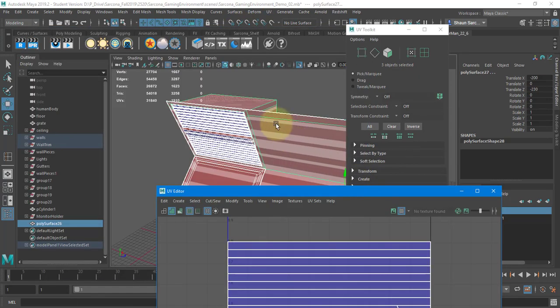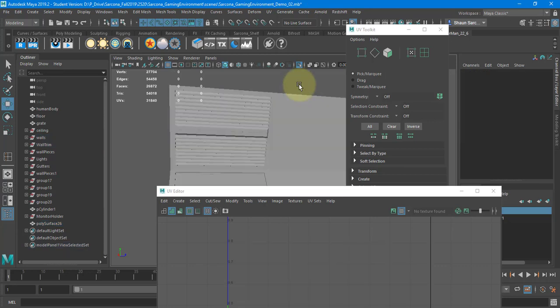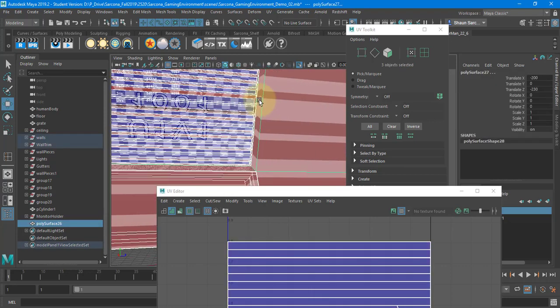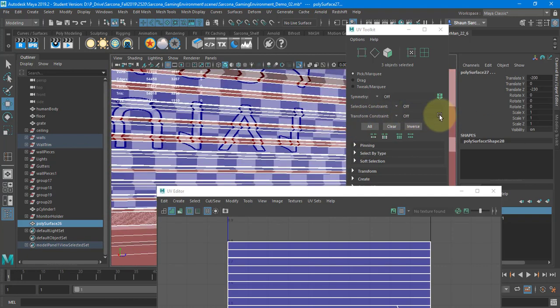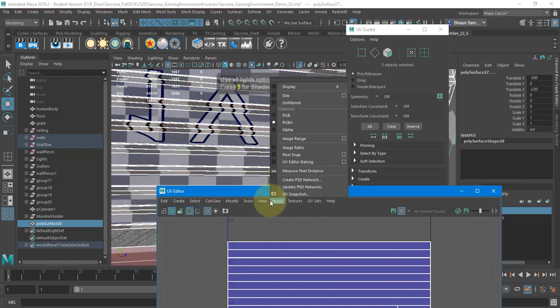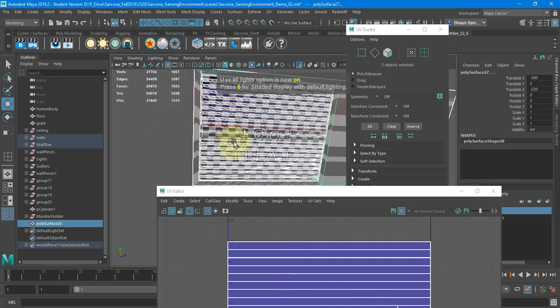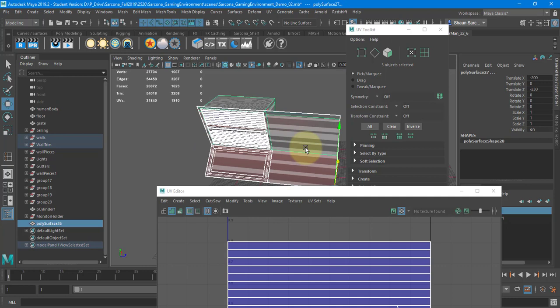While I'm in the UV editor, it's automatically going to show me checkerboards, okay? So if I were to click off this, they go away. If I click back on it, you can see there's definitely a checkerboard inside here. So here's a checkerboard. You can see it looks somewhat like checkers. They're blue. These are red. Let me turn off. There we go. And then this is also a checkerboard, but the UVs for it are totally crazy, okay?